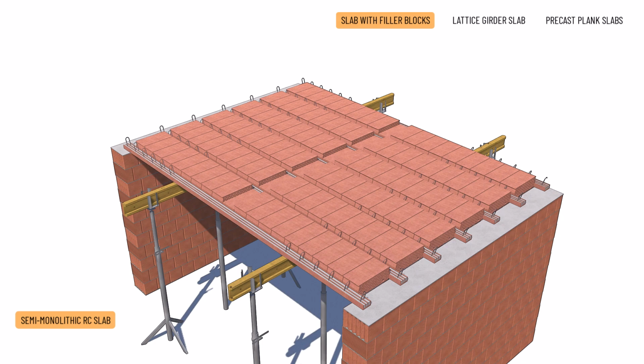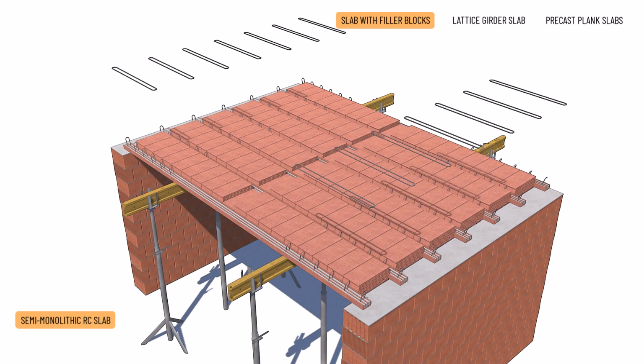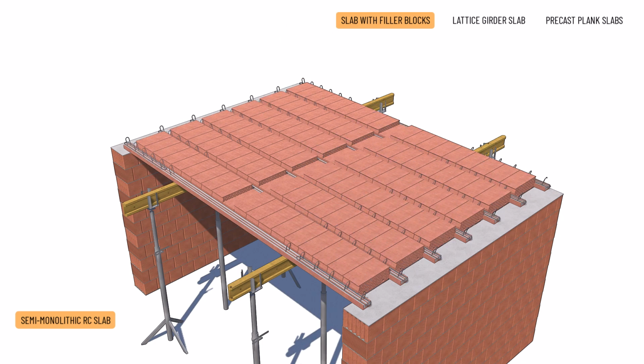The top reinforcement of the slab is constructed on site, with the bars leading through the stirrups. The joists are tied with both its top and bottom bars into the ring beam. The bottom bar is located on the top of the base of the joist. Its length is 200 centimeters, diameter 10.